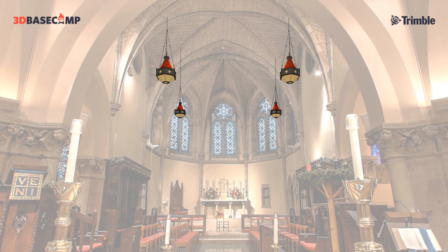Same thing, instead of in the SketchUp model, for the high altar pendants, it was a lot of detail to create. These ribs here were very challenging to create using Follow Me or using solid tools. That took a while to build in the SketchUp model. So instead of using that in this early phase, because we had the high altar lights done, we just used the Google Street or the 360. We just took a snapshot from the 360, used that as our view, and then faded that out in Photoshop.